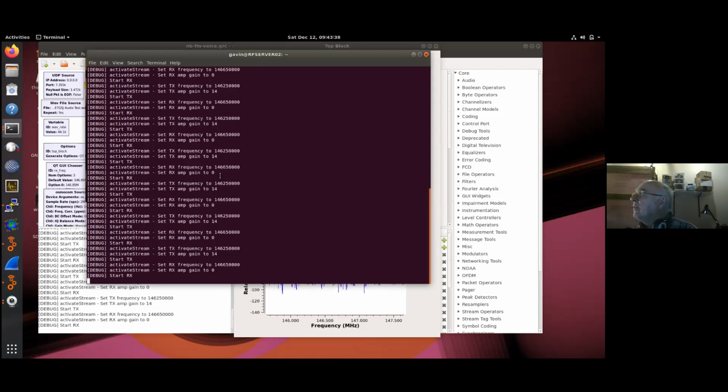Okay, Dave, N7LXR, did you use a microstrip connection from your amp to the SMA out? No, I did not. I basically cut the trace and I soldered the leg of a capacitor to the cut trace, and then the other leg of the capacitor, I went straight into the coax. It's really tiny in there, so there's no way I could have, but I did use a microstrip on one of my first power couplers. It was a failed one, but anyway.